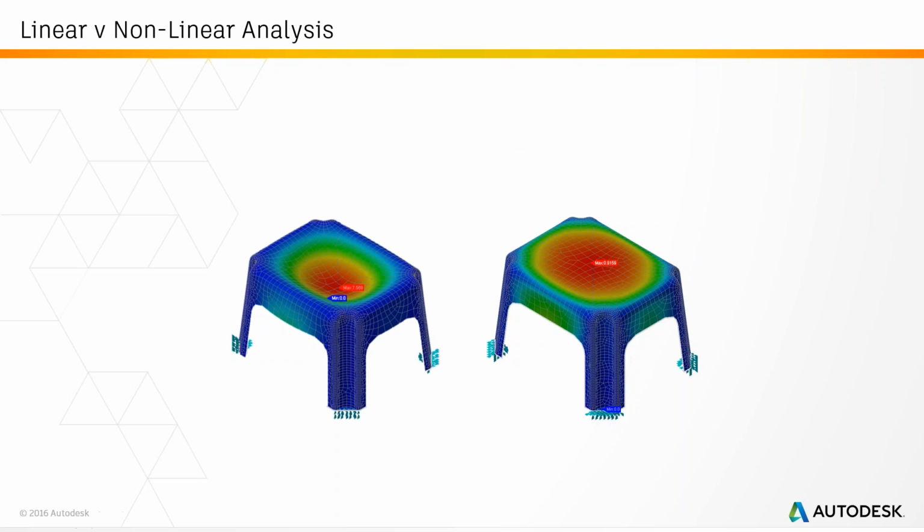On the last example, I'd like to show you is to look at linear and non-linear analysis. So what do I mean by this? There's different types of linear and non-linear. Typically a linear analysis, and some of you may be familiar with this, is where you apply the load, look at deflections and stresses. But the load is applied in one step. Stiffness is not assumed to change.